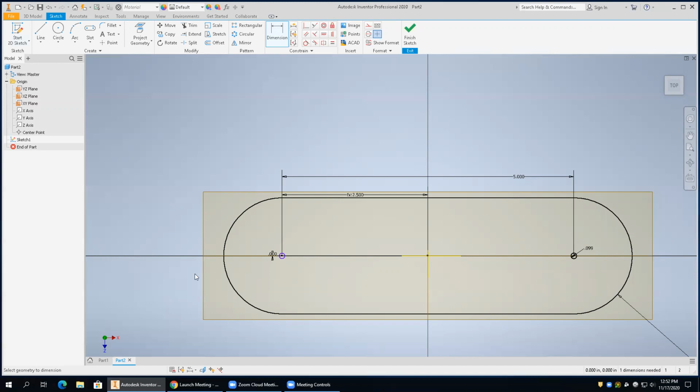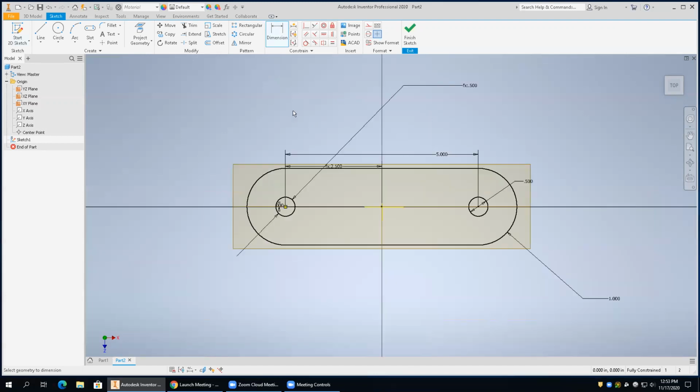Yeah. Okay. We good? 5 units, center. It's coincident with the planes, right? So the only other thing we need to do is set the diameters. So this little circle here, I'm going to make that 0.5. This one doesn't have a dimension, so I'm going to place a dimension on this guy, and I want that to be equal to that one. So just click on it and OK it, and you got them there. Everything's good now. With your dimensions, we got all the constraints we need.